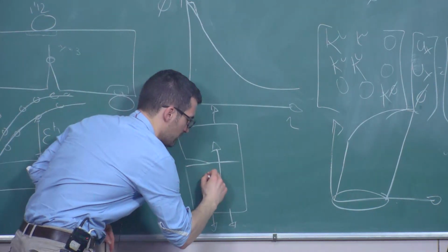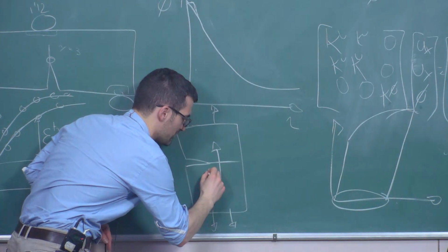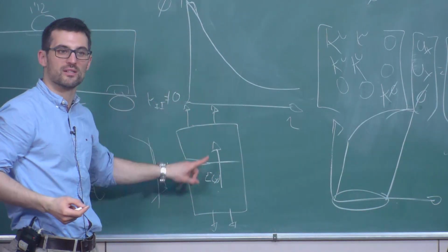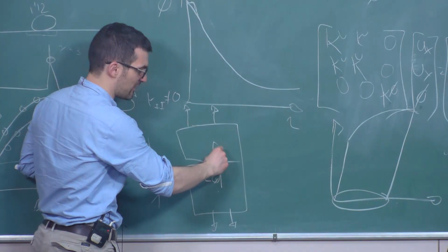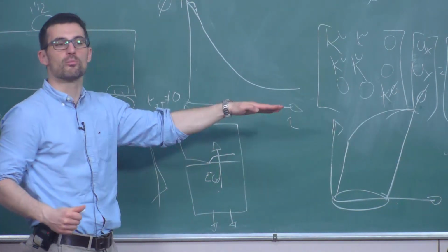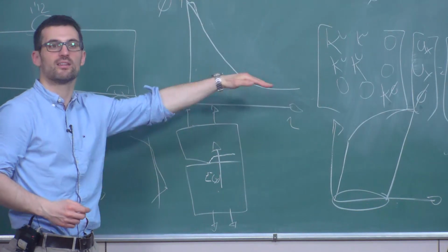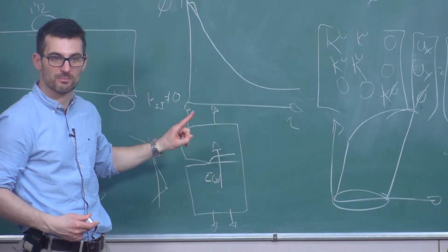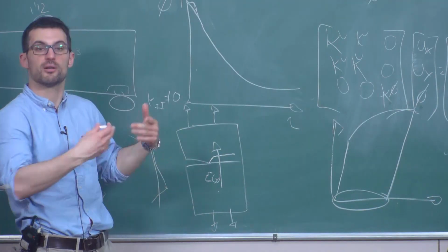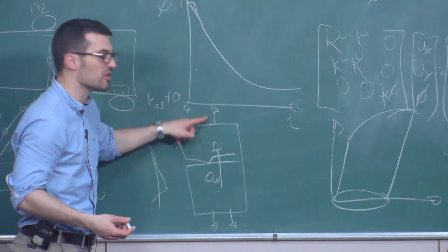This is Young's modulus that is varying in space. So due to the gradient in properties, you're going to get mixed mode conditions. So this crack will do something funny, and then eventually all cracks like to go mode 1 at the end of the day, so it will do something funny and then it'll go. And not only that, that's only if you consider the mechanical properties, but the fracture properties, of course, will also depend on composition, so they will also change in space.